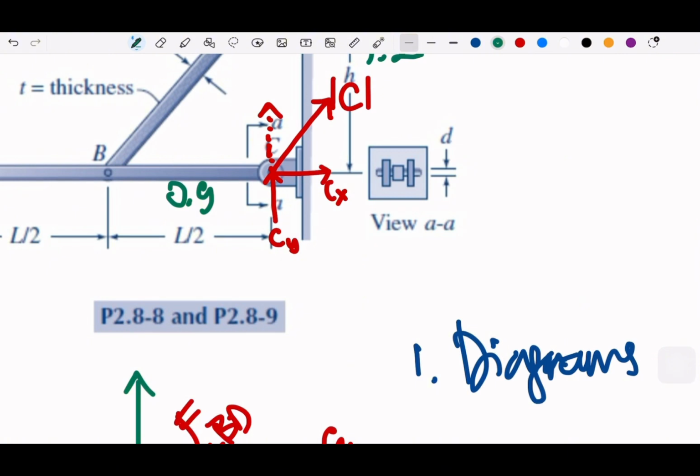Imagine that the forces will be applied here. If you see this view, you need to know that this will be about a shearing force. This is what we call the direct shear. And see, 1, 2, 3, it will be double shear. Double shear means when you divide the force by the area, you need to multiply by 2, or twice as the single shear, right?